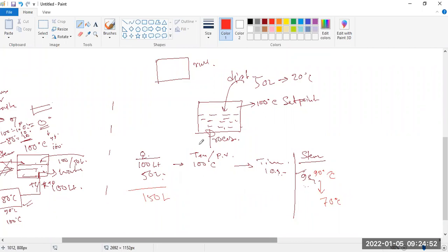But here is the feed forward control action. We know from the rule base or the experience. In academic language we call it experience, and in technical language you can find everywhere there is some rule base. There is a chart or the rule base. If 150 liter is there, we need, here is another chart, 100 degree centigrade. Then we have to flow say 15 seconds of steam flow. So the operator will allow it up to 15 seconds.